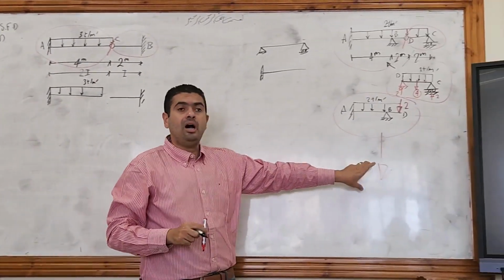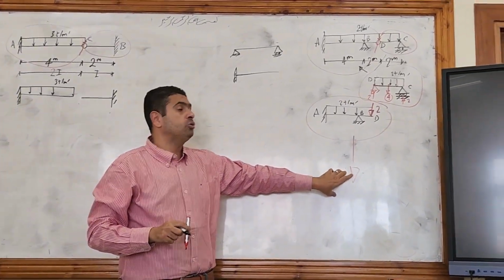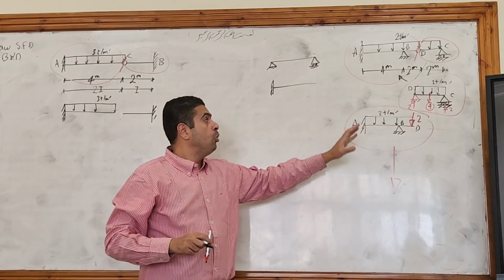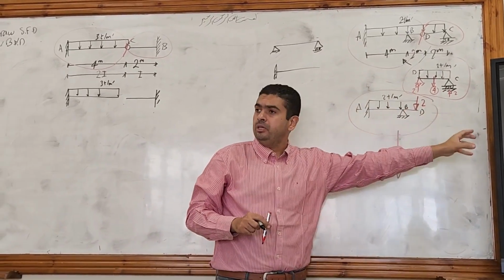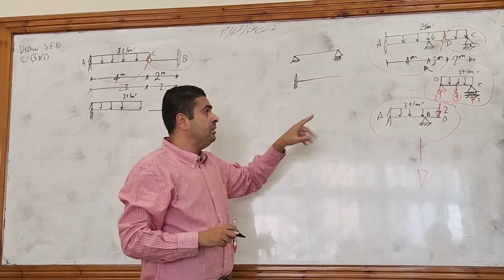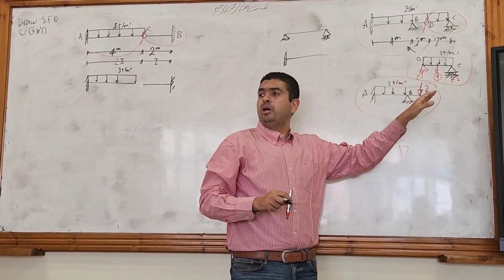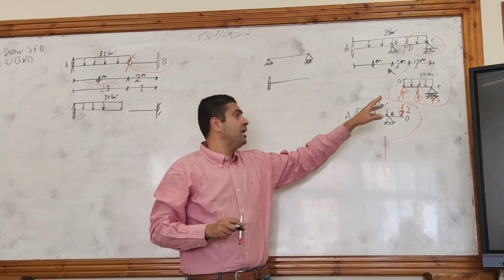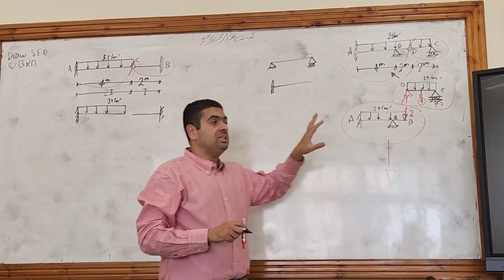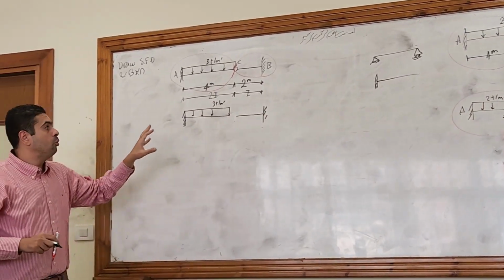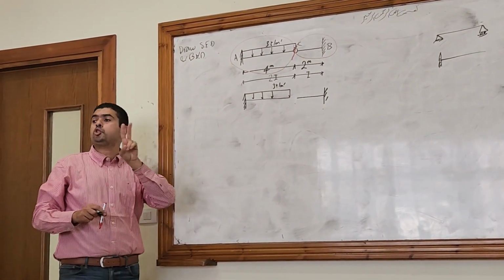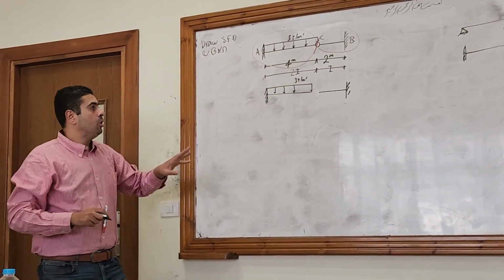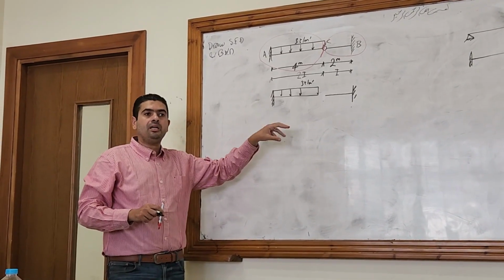So here I knew how to deal with a compound beam with a main part and a secondary part. Again, remove the secondary part, throw it away, but before you do this, you have to take its effect. But here, when dealing with a compound beam with 2 main parts, we have to deal with it like this.